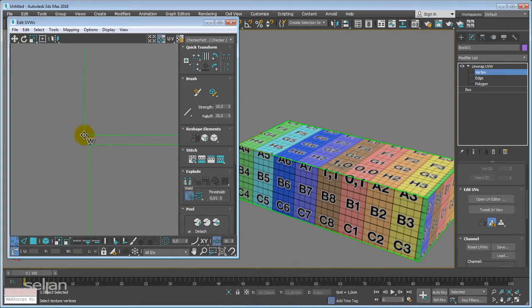Now this target weld is initiated. So I will drag this, holding down the left mouse button. As you see, it's switching to welding mode. I like to move it away a bit just to recognize I don't have any overlaps and there are no other coordinates behind this one. And when you are hovering over the matching point and releasing the left mouse button, they will weld. Alright, now as you see, we have two faces now and one corner is welded.